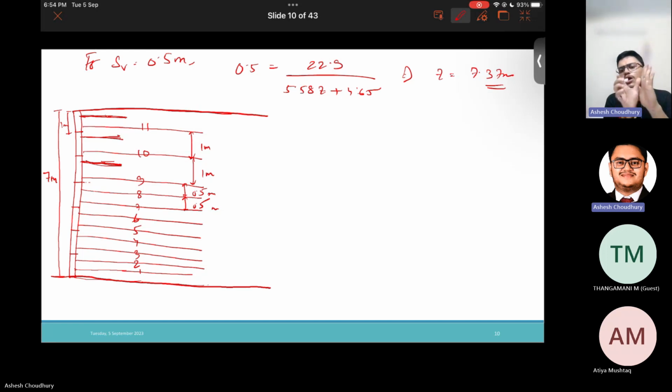So what we do, we attach some small reinforcement layers here also. Top and bottom both will have some reinforcement layers. So the eccentric loading will get distributed, and there will be less chance of displacement of the facing block. Hence these small lengths of geogrid are also tied at the top of the facing block.